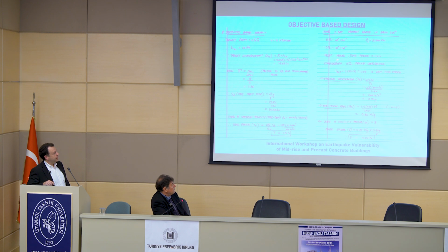This step takes a little bit longer than just a line, because you develop your SAP 2000 model or your ETABS model, and then apply the loads, the masses, the dimensions that you have. And the initial period estimated was about 1.2 seconds, just putting these dimensions into ETABS.